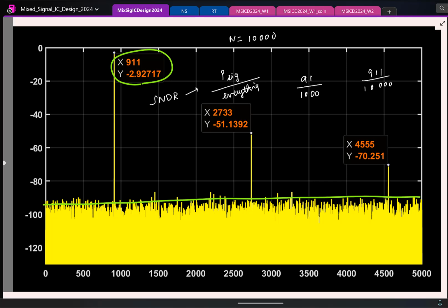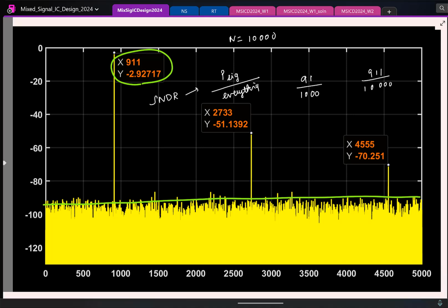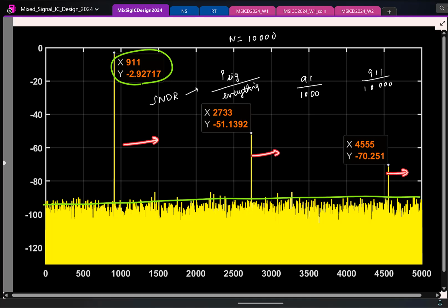Okay. Cool. So now let us say I keep increasing this input frequency here. What will happen to the harmonic frequencies? If I increase the input frequency, the harmonic frequencies will also increase, right? And if I keep increasing beyond some point, all these guys will go up. After some point, this one can go beyond fs by 2 and it will alias back.